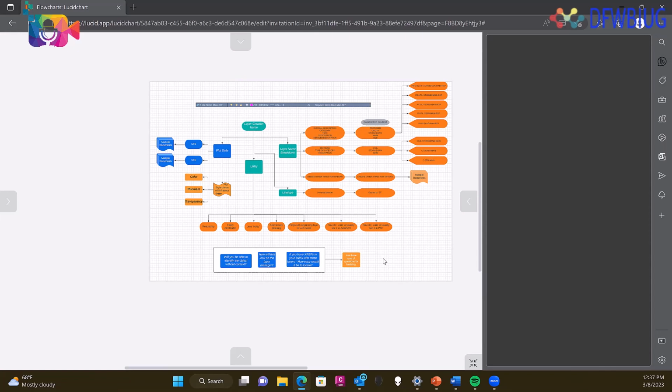Yes, you can do filters and layer states and stuff, but don't go crazy and have a template that has 1,000 layers in it. Yeah, I saw a master template. Not one somebody built, but a government agency provided 7,000 layers in a master template. Of course, this master template was really just like, hey, here you go. You can use this government agency template, but it's for every discipline.